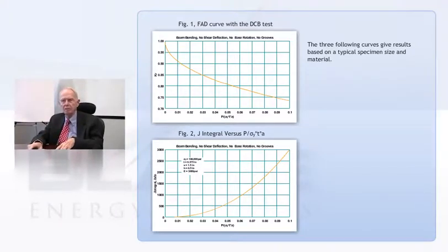If you do that, then you can include what I'm calling the base rotation with the shear deflections, and you get something real nice. And it's an improvement over the solution that only includes bending. Another thing that's done is that on these samples, it's not indicated on anything here, but where you cut with a saw, you frequently cut a groove in each side. And that's because, life being what it is, sometimes when you pull on these samples, the fracture doesn't progress just straight ahead.